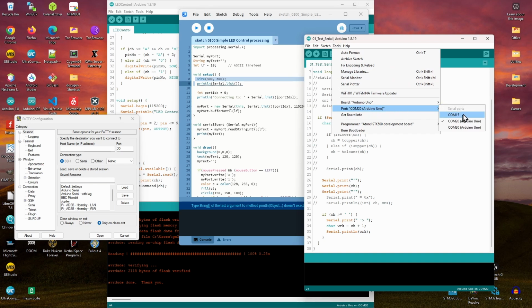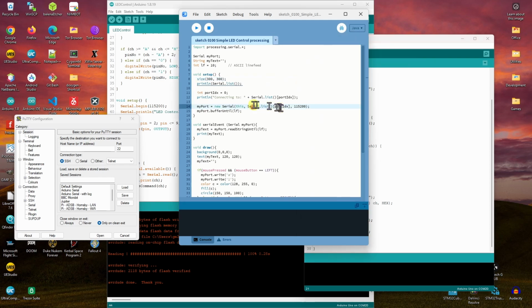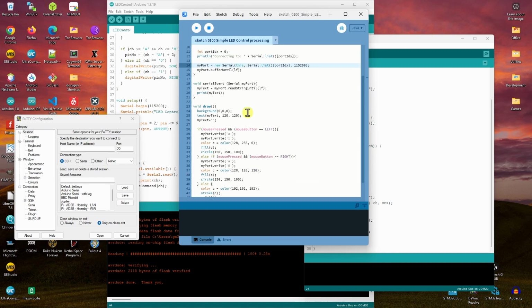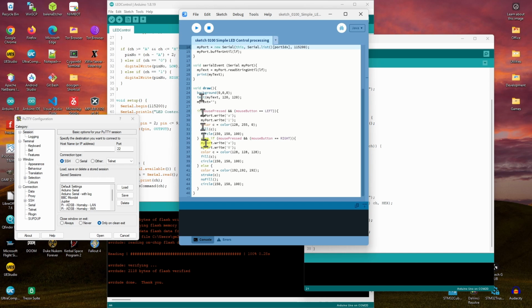Well, it probably won't say 15, it'll say COM20 and COM30, because I don't think 15 exists anymore. Hopefully it won't say that, because it then connects to the first one and uses that speed. So it connects to the serial port, and then it sets up a little reader to allow me to see any messages that come back from it.